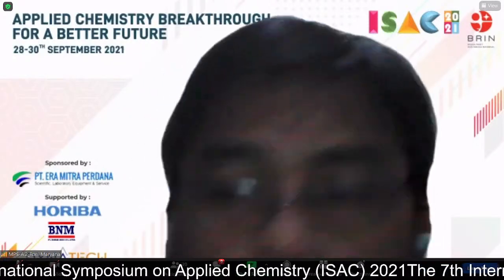For the first question, I will answer it. C1 is the result of mixing calcium carbonate with chitosan, which is cured at 100 degrees Celsius for 60 minutes. There is a very visible oxygen and hydrogen bond because the sample is not as fused as the others. So it's very possible it's water that is still trapped. So the oxygen and hydrogen bond is very clearly visible because of the water.